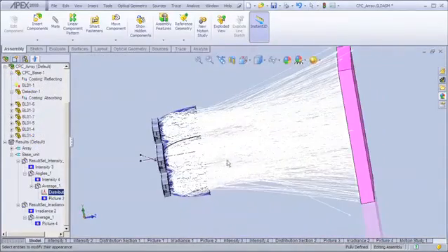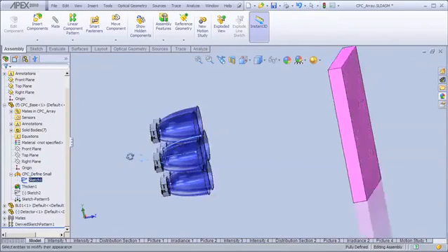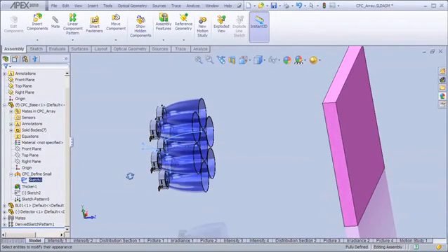The other thing to mention is that the CPC is an equation-driven surface. In this particular case, I've defined a CPC for a 3 millimeter input radius and a 30-degree output cone. If I need a system to use a different sized LED, so a different input aperture size, or if I want a different angle of output energy, all I need to do is go in and modify the equation-driven CPC definition, and I have my new CPC.